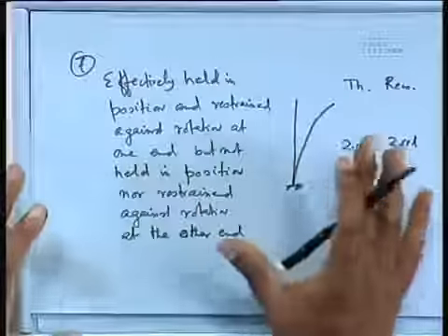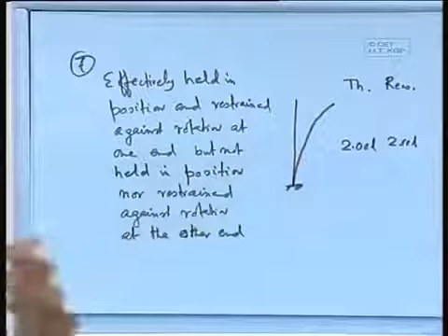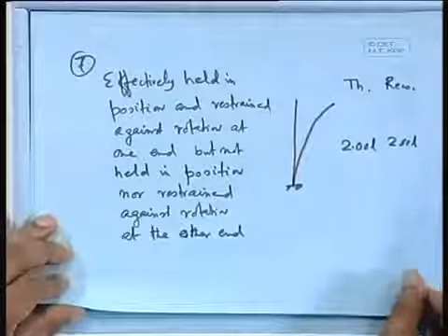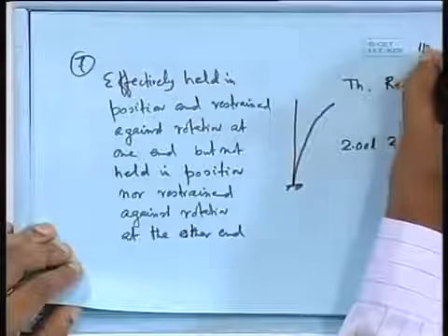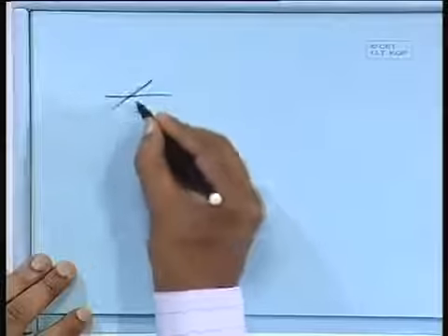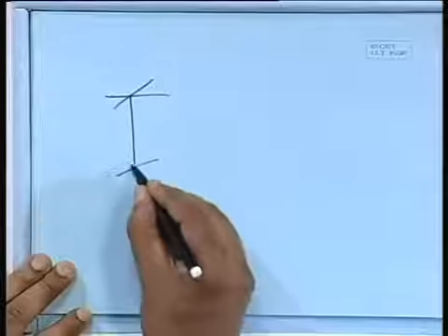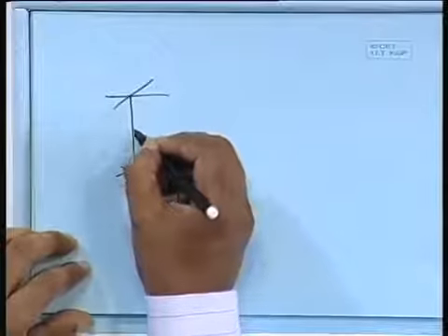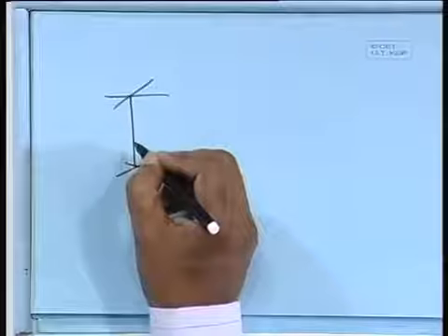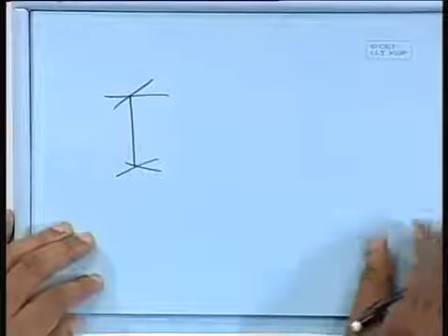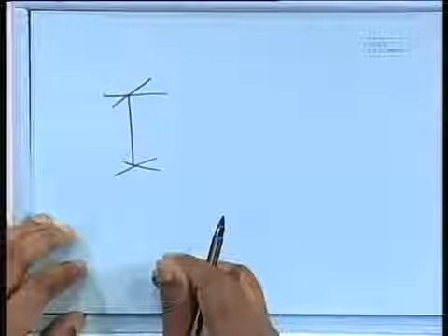So this is the general case. If it is a framed structure, then how shall we find the effective length? In that case also we can find out the stiffness, and we have two more figures in that code. I think we shall come to it in due course when we solve that multi-storied frame design.